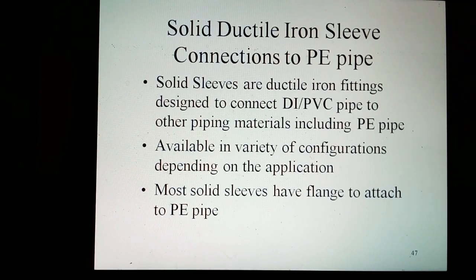On the ductile iron pipe side, the metal flange is attached to the pipe and a gasket is installed over the pipe and into the sleeve before bolting the metal to the sleeve flange. The standard MJ adapter is used on the PE pipe side to complete the assembly. Be sure to use the manufacturer's recommended bolting procedures for this assembly.